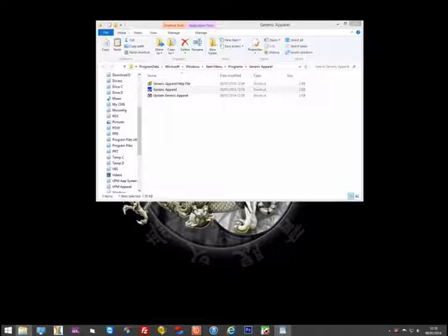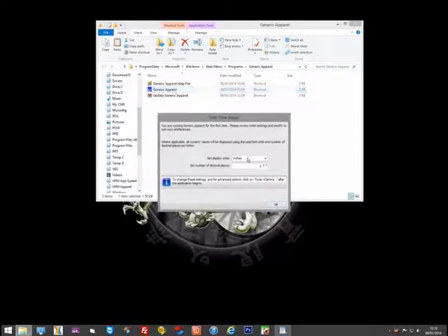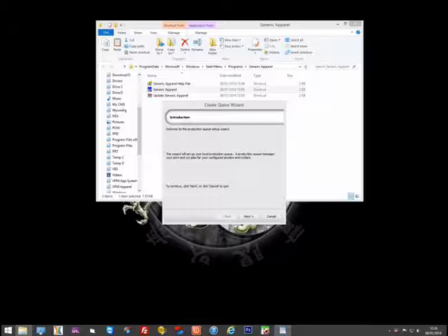Once the installation is complete and your computer has restarted, you can launch your apparel software for the first time using the shortcuts created. The first time you run the software, you must select your preferred units, inches, millimeters or centimeters, and the number of decimal places you want to be able to use for accuracy. You will then proceed through a setup wizard for installing a printer.